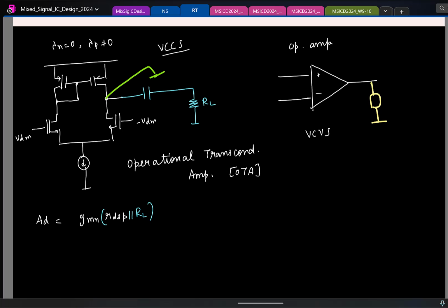And of course for an op amp this is the symbol. So for the OTA we need a new symbol, and the symbol is basically a quadrilateral instead of a triangle. The idea is the output current of this block will be constant and it will depend only on the differential voltage you have applied, right? So the parameter is the transconductance, GM, and this will have its own output resistance.